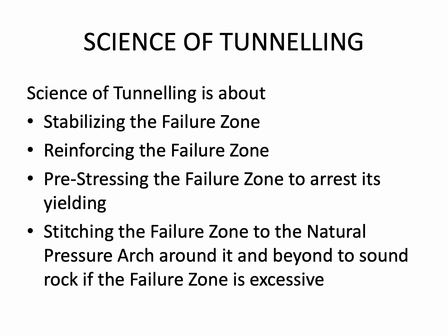Stitching the failure zone to the natural pressure arch around it and beyond to the sound rock is an additional, fourth measure, required when there is an excessive failure zone around. In most cases, stabilizing the failure zone by various methods, and also if required reinforcing and pre-stressing the failure zone, stabilizes the excavated profile.